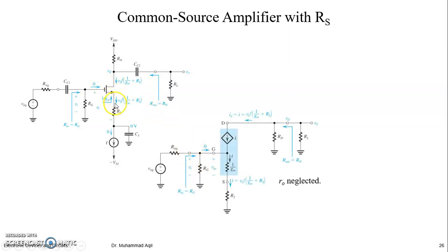How to replace this one? Because we have a source resistance, it is better to take the T model instead of the pi model. So replace this with the model. Here is drain, here it's gate, here it's source, right? This is the model, I, or we can say GM VGS, right? And this would be, what? 1 by GM, and the voltage across this resistor will be VGS.